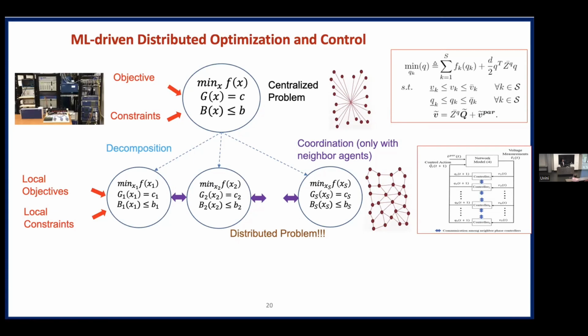So then you get an objective function defined, and we always have constraints, which could be equality and inequality. In distributed control, we take that and decompose it into each node. Now, of course, the constraints will become fewer, right? There will be only one set of equations there. Control variables will be only for that node and the neighboring nodes because you're getting the data from there. And once we distribute it, then there are some boundary variables shared between two different nodes. And we can share that by exchanging the information right here.